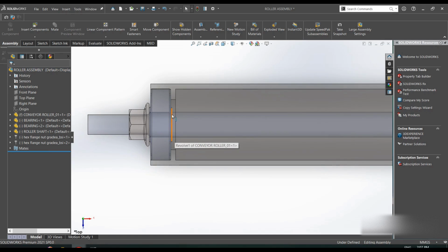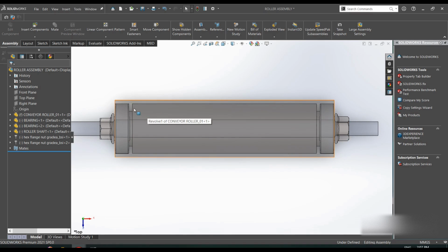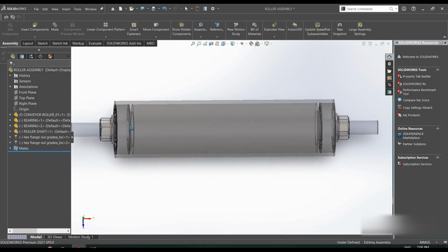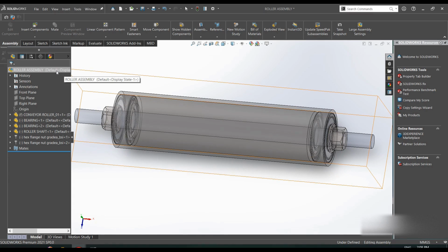So you can have a look here. You see, this is our bearing here, and this nut will be resting on the inner race of the bearing, and the same on this side. So this outer covering will be moving with the outer race of the bearing. So the inner shaft is all stationary. Yes. The design is applicable, of course, and it can work. So this is how it is designed in this case.